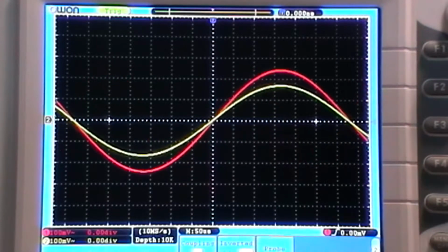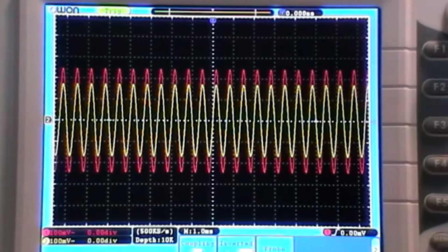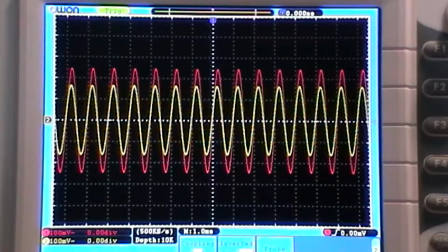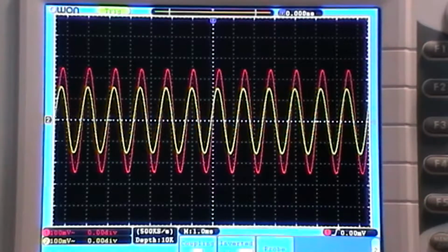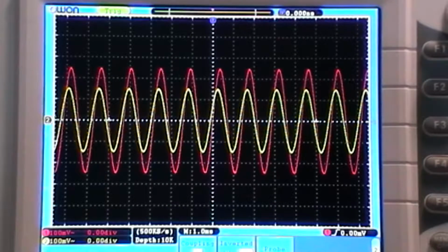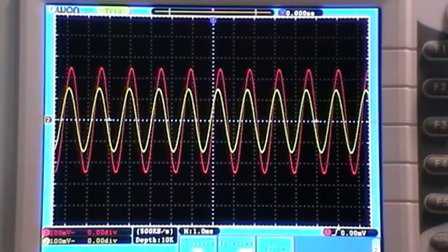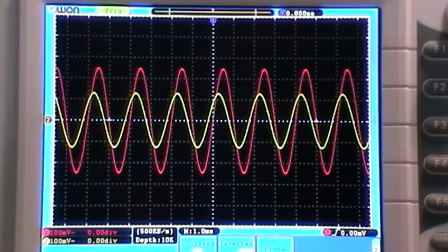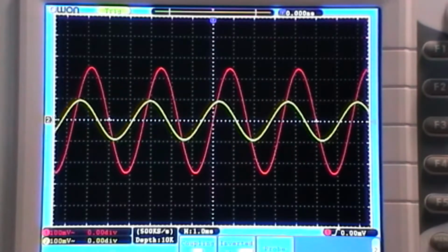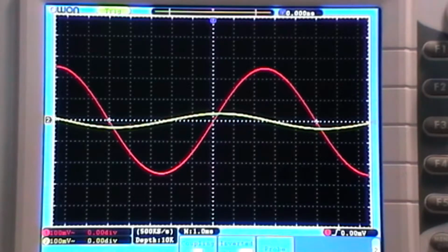Again, now I'm going to change this so I get a lot more on there, because when I crank it down to the high pass cutoff point, which is about 700 Hertz, as you can see, the phase shift is now shifted the other way to the minus phase shift. It's going that way in the phase shift because it's the high pass filter cutoff point that's now affecting the signal. As you can see, if we go down 1 Hertz, yeah, it's almost killed it off. So yeah, that seems to work really well, really. I mean, it does what I'm expecting it to do.